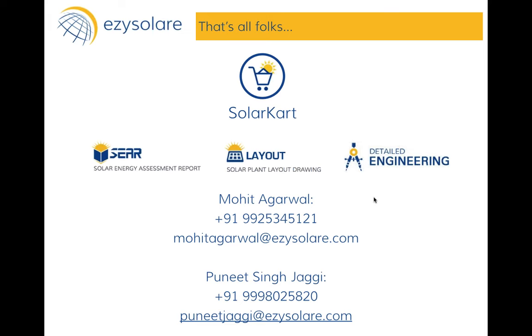The next question is how to calculate the correct tilt. Again, there is a broad rule of thumb that the tilt of any particular location should be the same as the latitude. But ideally, you should use the sophisticated software that we have at our disposal. For example, PVsyst, which is the most commonly used industrial software, to find out the tilt according to a particular location. You could also get the same in the Solar Energy Assessment Report, which you can probably explore on solar design.